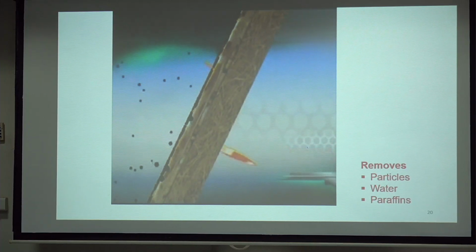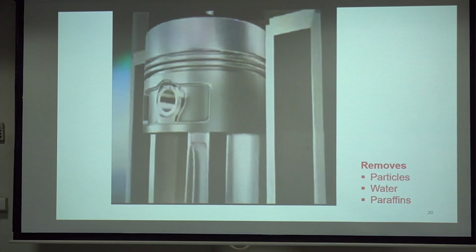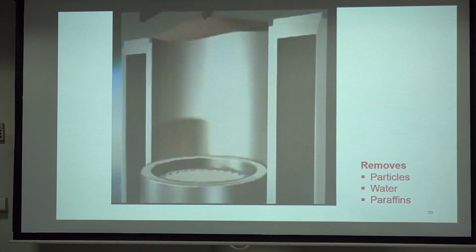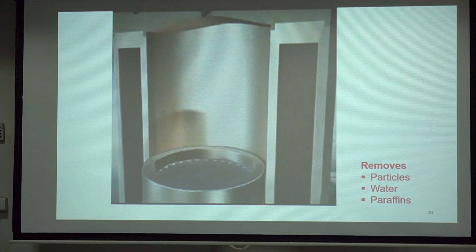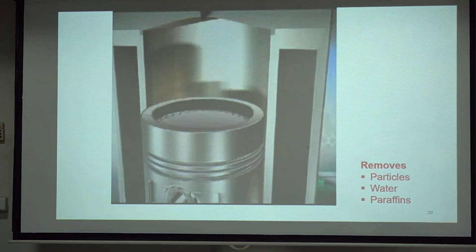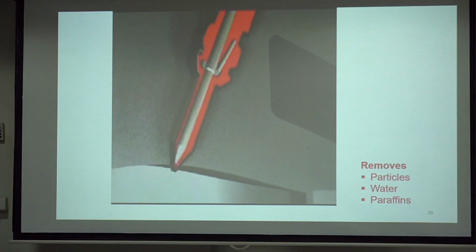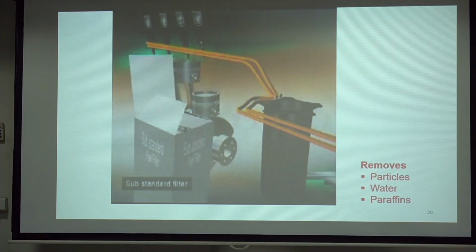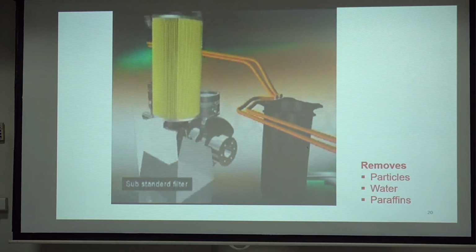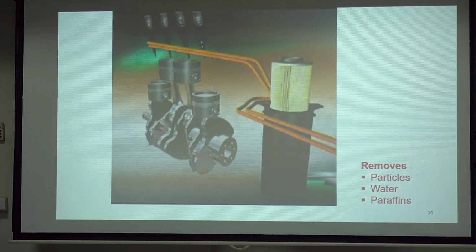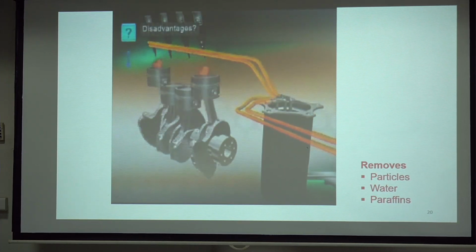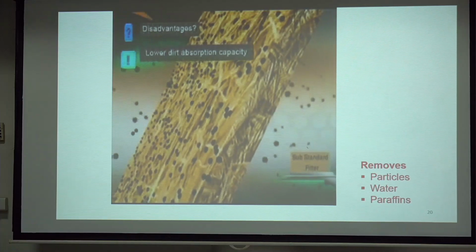Guard filters ensure maximum engine output and prevent coking at the injection nozzle and corrosion damage to the injection system through ideally filtered fuel. See, the injector nozzle should not get blocked. If there is a particle, the injector nozzle will get blocked. That is the problem. Low-quality filters often have a whole range of disadvantages. For example, casual filter media cannot hold back fine dirt particles.